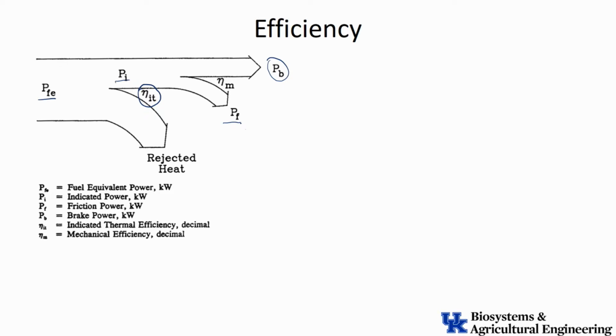So, a lot of it is friction. It's bearings that have to turn and so forth. But there's also some cooling that has to go on in the engine. So we have to pump water through an engine jacket to keep it cool on a lot of our engine designs. So that's all going to be a parasitic load. We often have a radiator in front of the engine with a fan, and we attribute that to losses. So all of that is losses, and it comes down to what we can get out of this thing.